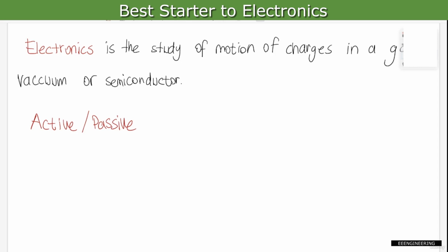So the time average, all right, I'm reading the definition. The time average power delivered to the device over an infinite time period is always greater than or equal to 0 for passive elements. And this is, I think, confusing as heck. As an instructor, I'm not having any problems with understanding that definition, but it is a little bit over the line. So what I'm going to say for a passive element is really simple. A passive element does not supply power to the circuit. Simple as that. And the formal definition made in the book is not wrong. It is totally correct, but it takes a little bit of time.